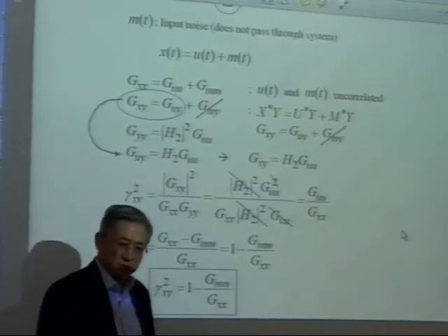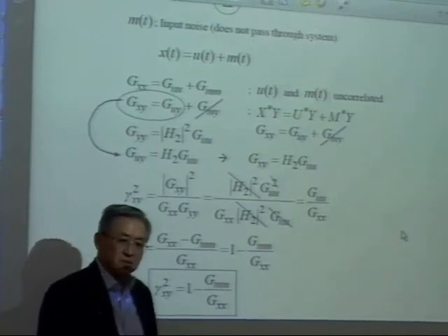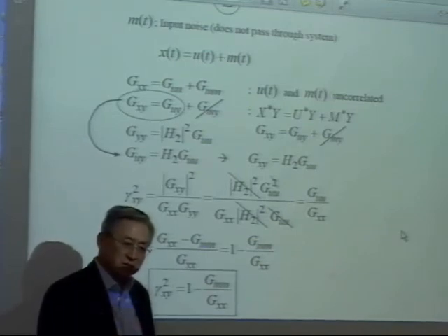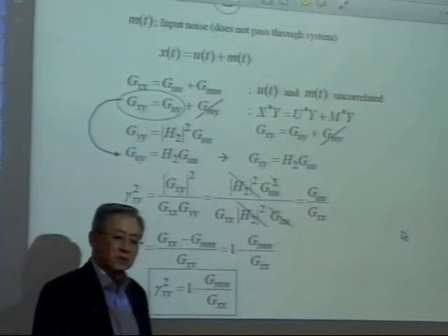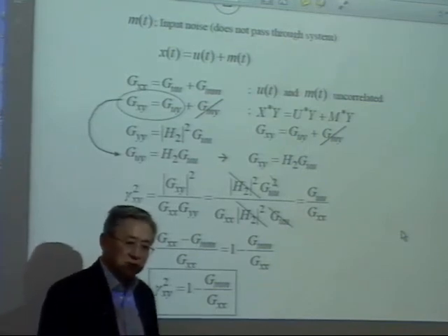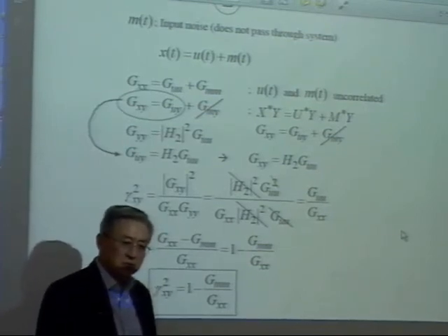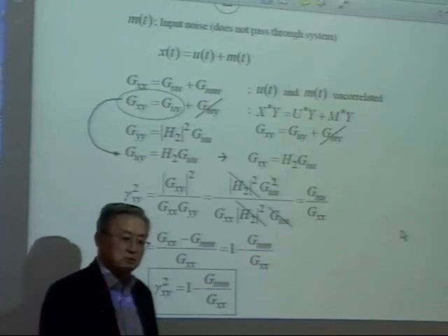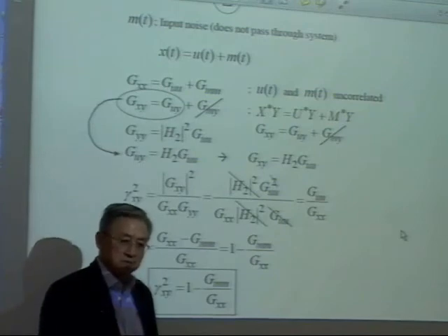You can compute that and say, well, this particular system has a problem because you have a lot of noise coming from the input side or the output side, or the transducer could have a defect in there. We have to change to a new transducer, or vice versa. You can determine the things and take action. Okay?